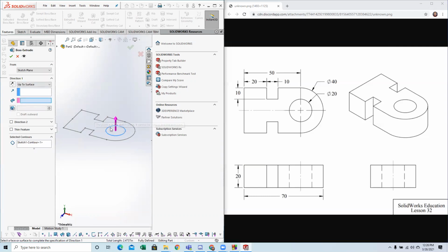So it looks like the sketch contour I chose, it's only choosing one of my pieces. Or, hold on. Okay, so I had to redefine that one. I had to select this inner portion because we don't want to extrude this circular region. That should be a hole. And we just want to extrude this blind, which means we're just going to go a certain distance.